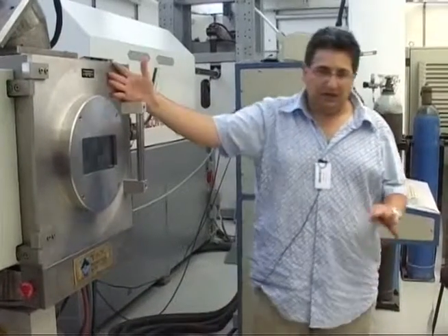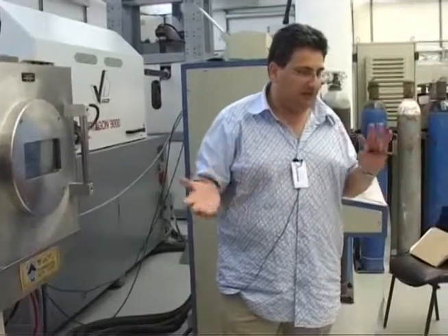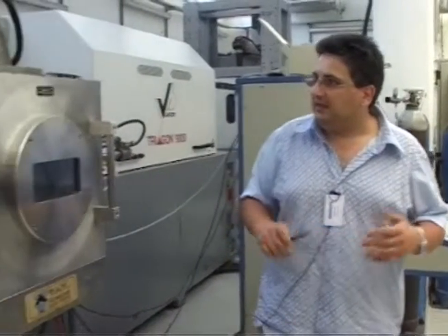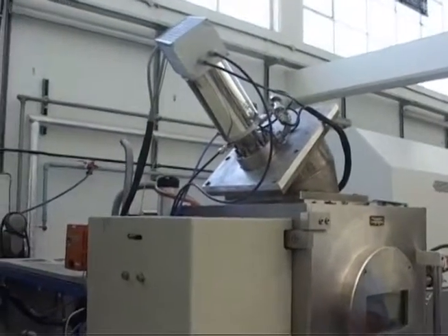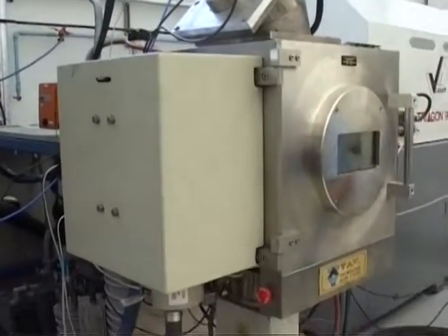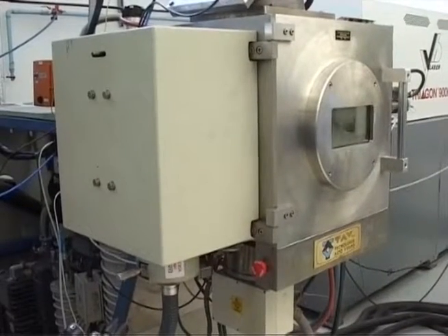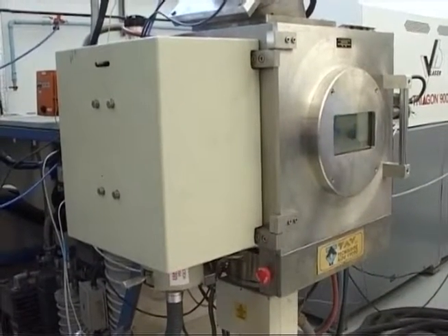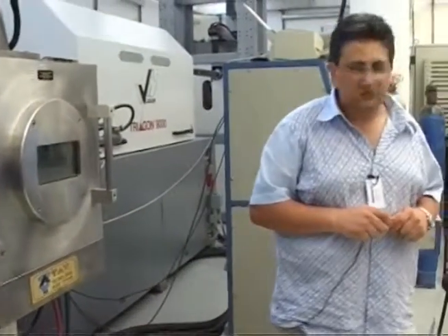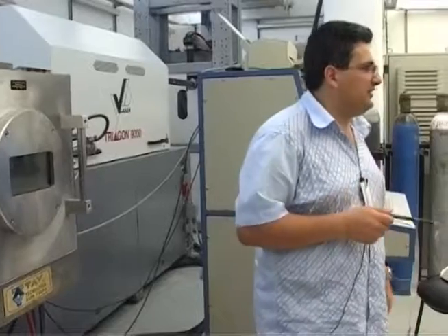Now, having an operating range between 20 and 60 degrees C makes this machine suitable for almost all engineering materials, and the fact that all components of the coatings are controlled electrically introduces a high degree of control on the process. Also, because the chamber operates at room temperature, it is possible to incorporate a wide range of sensors and optical devices which can monitor the coating process in real time.